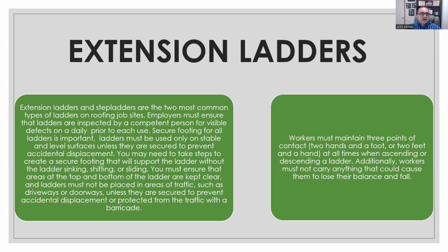Secure footing for all ladders is important. Ladders must be used only on stable and level surfaces unless they are secured to prevent accidental displacement. Again, being level and on solid surfaces are most important, unless they're a fixed ladder going up. You may need to take steps to create a secure footing that will support the ladder without the ladder sinking, shifting, or sliding. So not necessarily you're going to be on site where this condition is going to exist. You may have to create a condition that meets these standards.